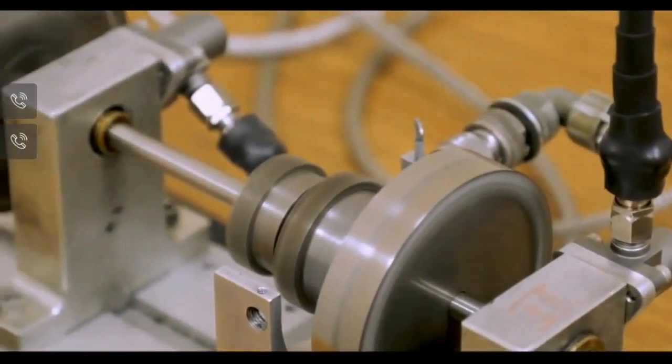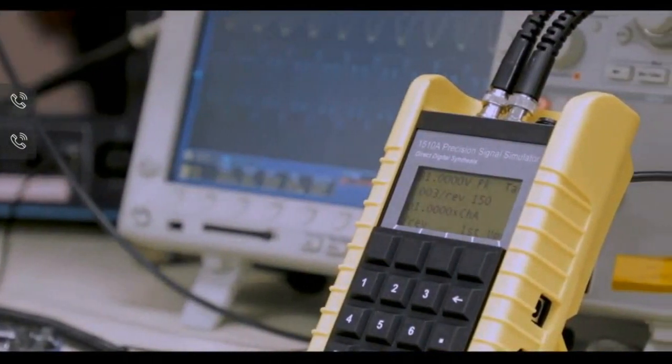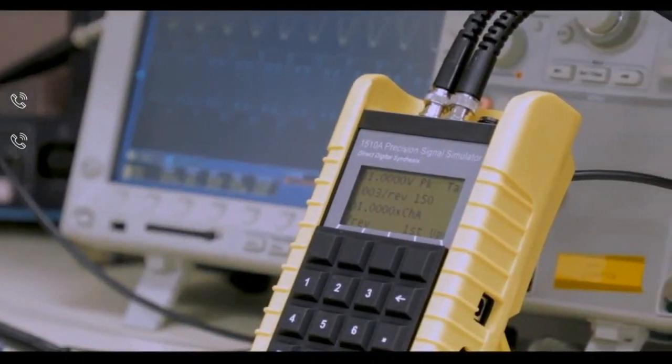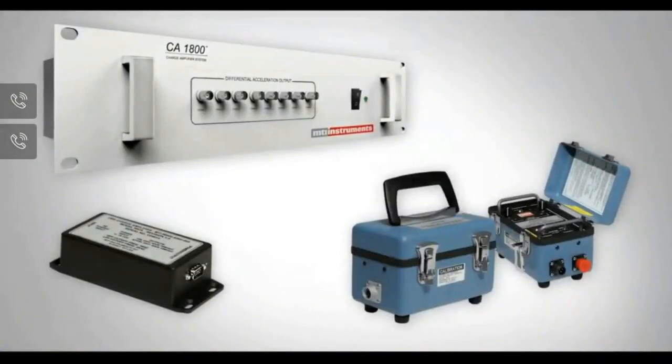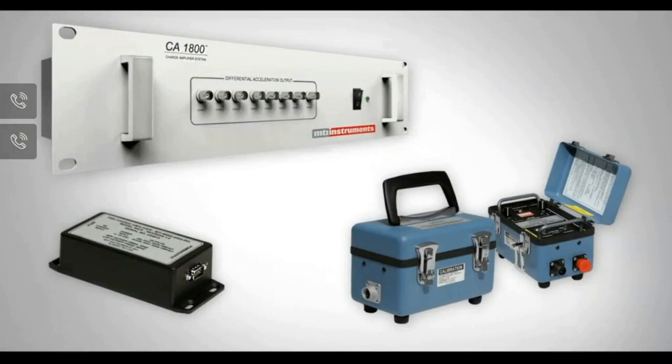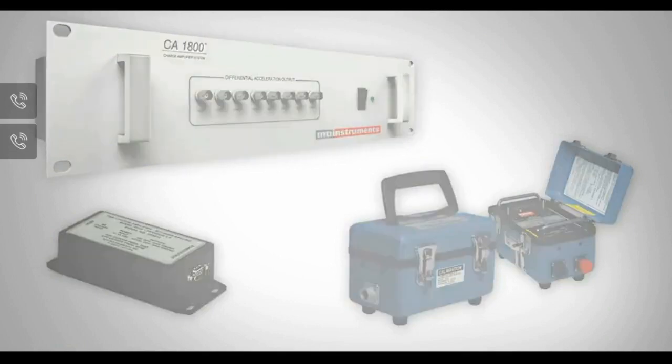These simulated signals generated by the 1510A can be used to test and calibrate charge amplifiers, which are used to condition the output of piezoelectric sensors. This is important as the signal response of charge amplifiers can change over time due to damage or natural drift. Periodic calibration is therefore necessary for accurate measurements.